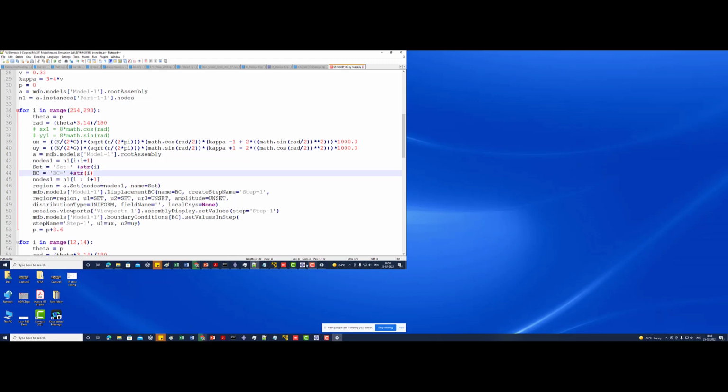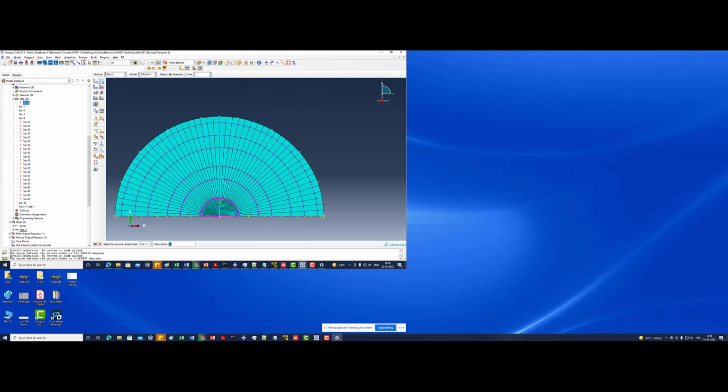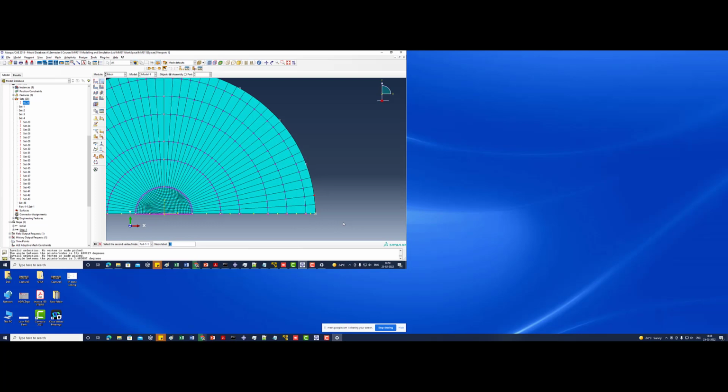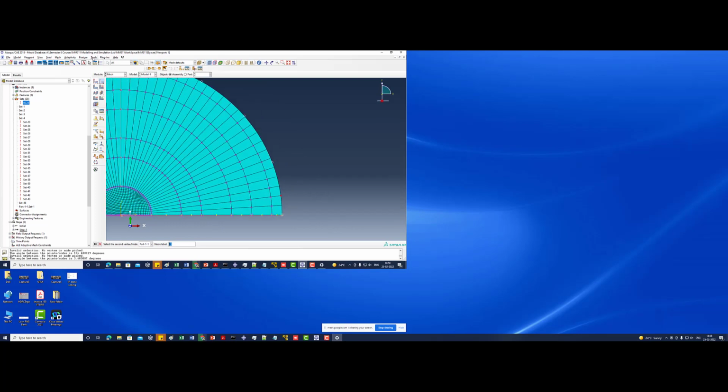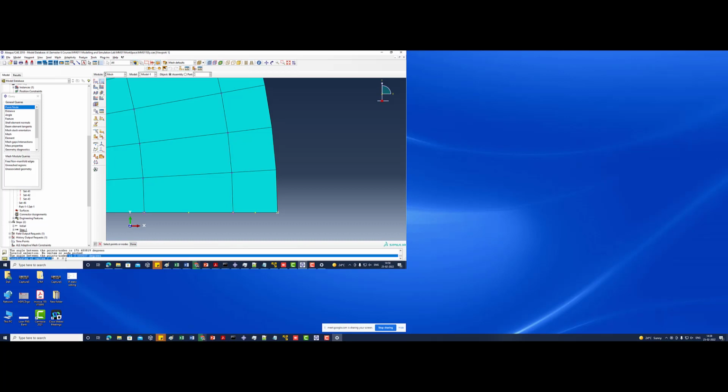Now we have to see in our model where the nodes are starting. Usually in Abaqus, when you do this kind of meshing, it assigns numbers to the nodes in a particular order, and we have to be sure that they are in order. Only then we will be able to assign the boundary condition based on node number coding. So let us find out what the node number is here. It will not be possible to find out the node number here because there is a vertex also. It will simply tell us the vertex, which is 2, and the coordinate value.